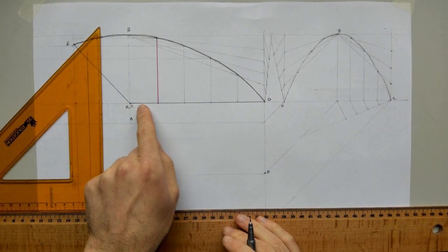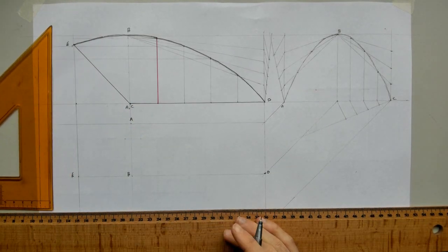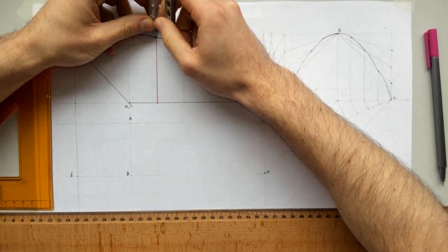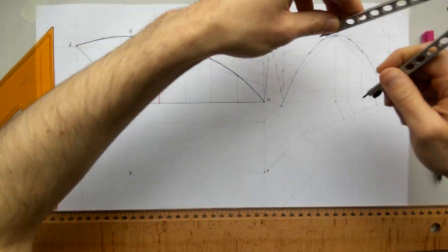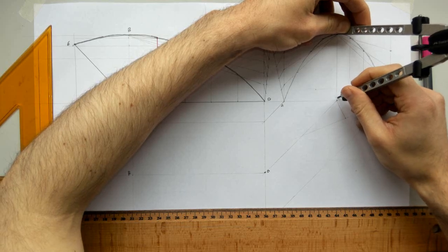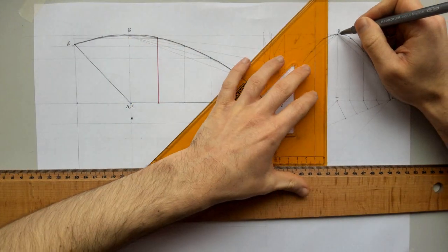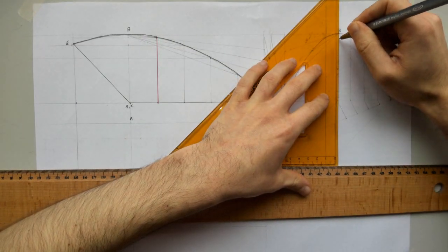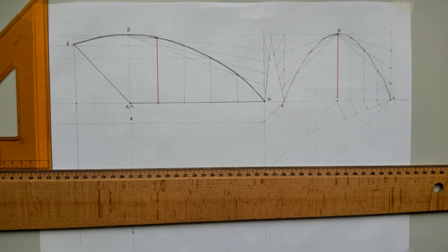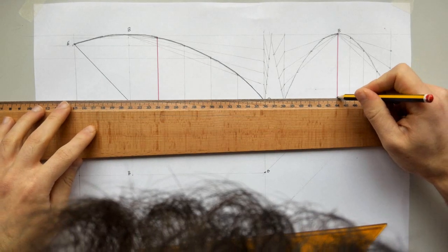So one of our widths we were given. So we had to divide this into 5 equal parts, basically using 30 mils all the way to get 150. That pink distance there, if I take that on my compass, so the height from there to there, I mark it from the top of this one, I'm going to get a width. So I just show that in pink there again. Them two distances are the exact same, taken from the vertex of the parabola. I'm going to get two widths from that then as a result.